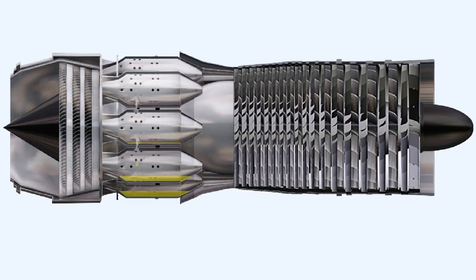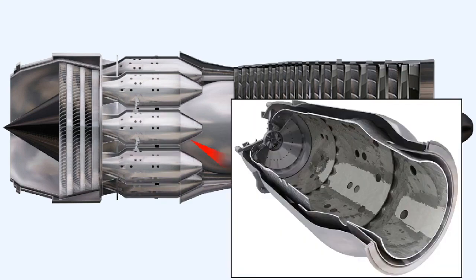Fuel remaining after a wet start will attempt to find its own level by flowing from the top of the engine to the bottom chamber. Once in the bottom chamber, the excess fuel exits the engine. Any remaining traces of fuel within the engine must be evaporated. To this end, the engine must be motored over on what is termed a blowout cycle.